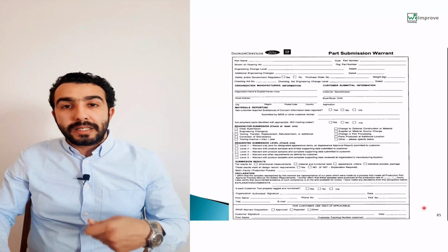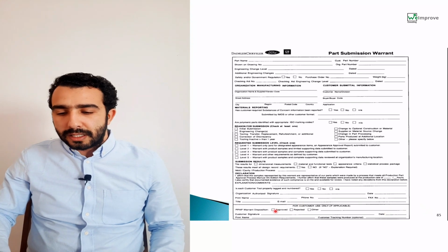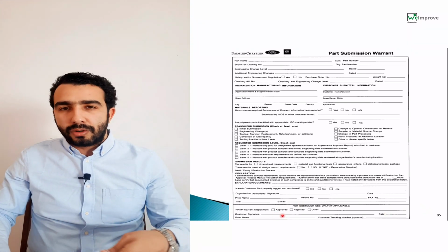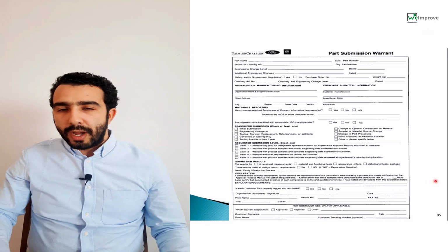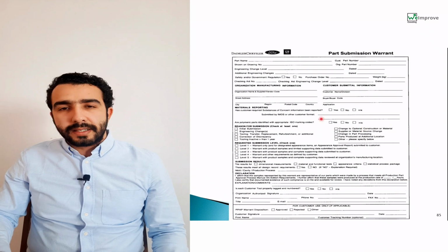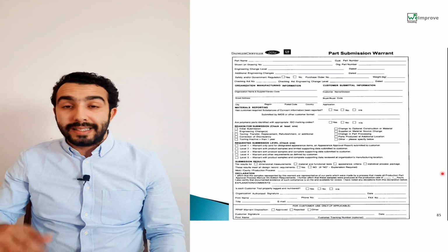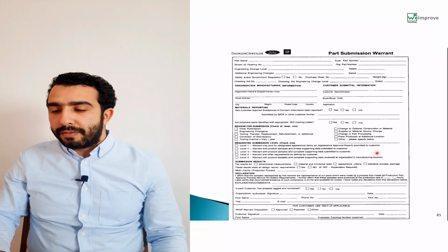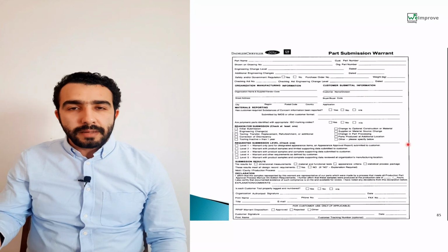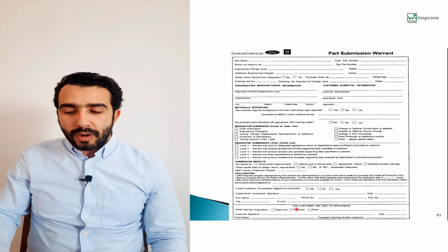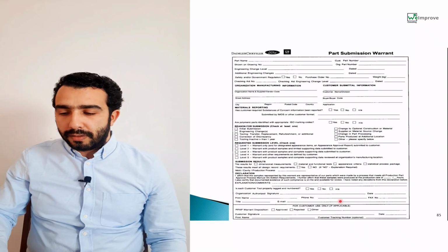So you have to submit a new PPAP before the expiration date of the interim, and then the customer should put his signature, his name, and so on, just for traceability. So you have to have this PSW for all your products with the approval of your customer. And if you are the customer, whenever you receive the PPAP package from your supplier, you have to check all elements to see if they are okay or not. Then you have to give them your status: approved, rejected, or interim.